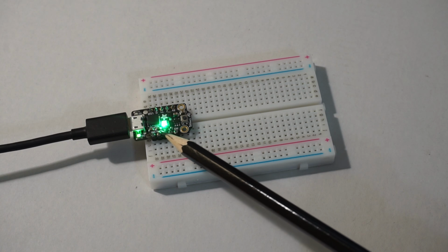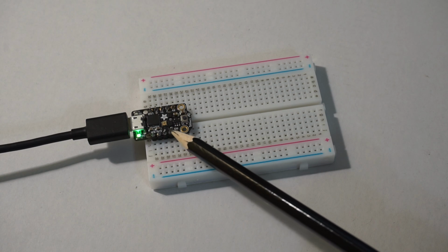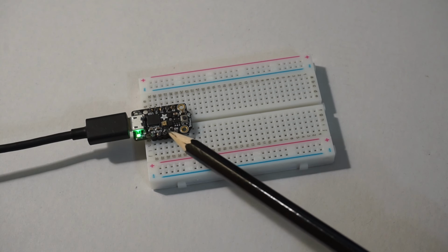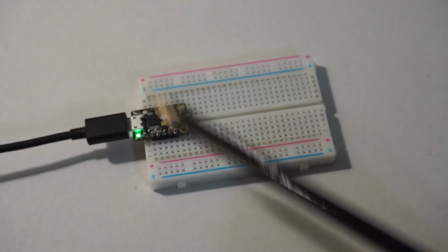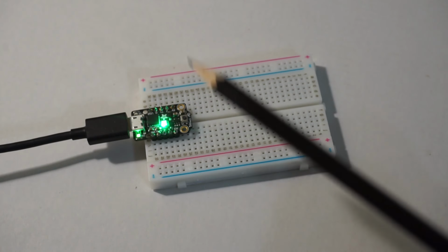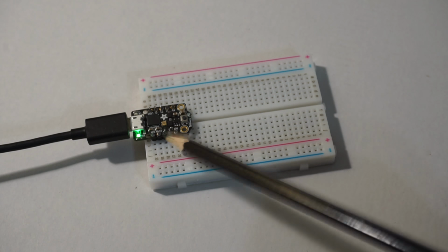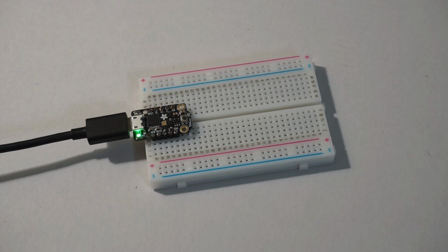So let's count it. We see 1 flash and then 2 flashes. That's actually the tens and the units. So 1 flash of 10 is 10 plus 2 flashes of blue. That makes it 12. So there's an error on line 12, and the white actually means it's a name error. That's right because we've changed the name of the word false there, given it an extra E, and false is an unknown name. It doesn't know what it is, and so that's the error. So if we fix that, then it will go away.